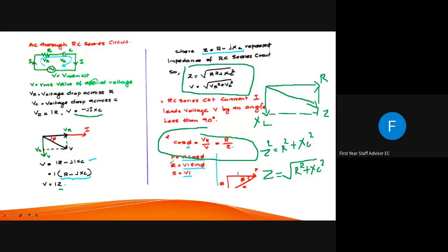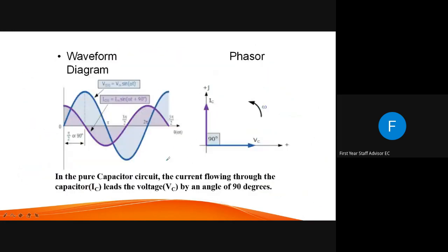And then later, what about power? I was also explaining the power. You can draw this waveform and divide it into four quadrants and say that there are two positive half cycles of positive power, two of negative power, and if you add everything, it will become zero. So average power is zero. You can prove it like this if you know the concept.